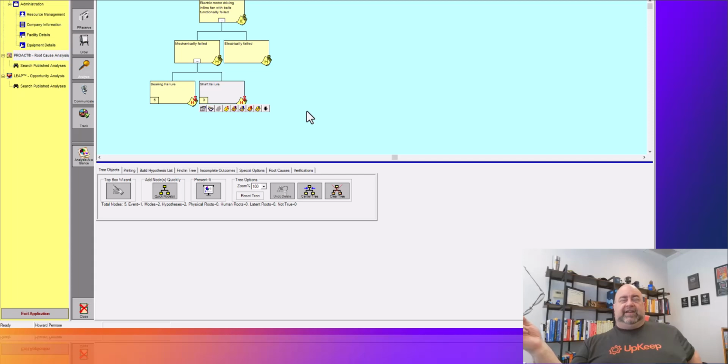Well, as a matter of fact, it turns out for one of the additives in that particular oil, it was aggressively attacked and turned gummy and sticky and came apart. So it turns out instead, Buna N turned out to be the perfect material to use, which, by the way, was an order of magnitude of 10 times, meaning it was 1/10 the cost of the Viton. But we didn't discover that. It wasn't even a consideration until we just happened to add it.